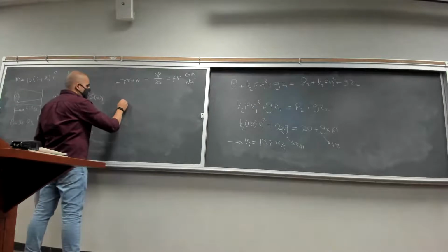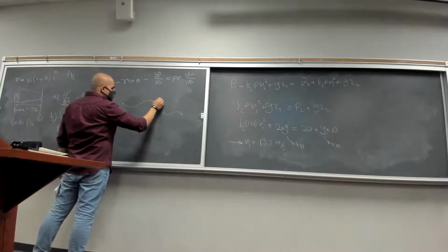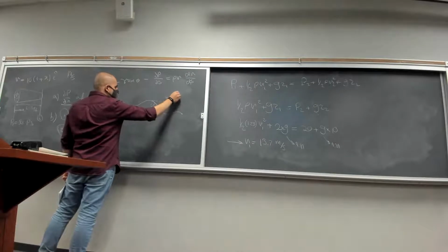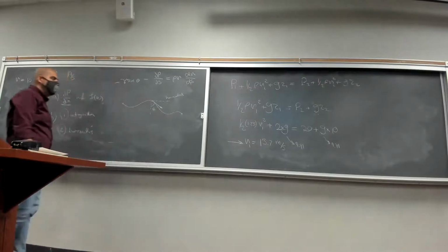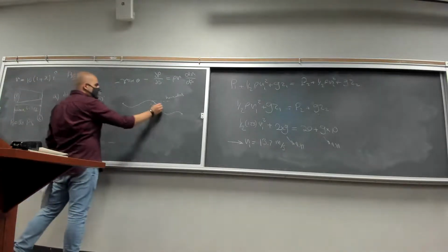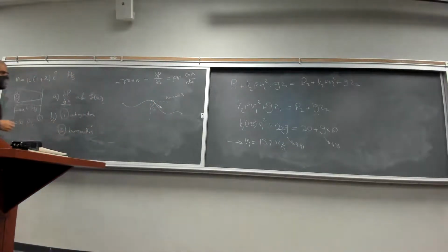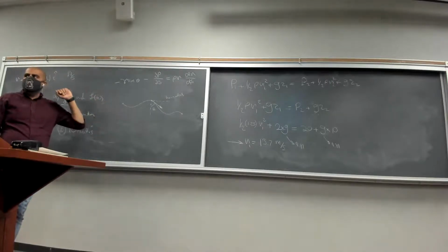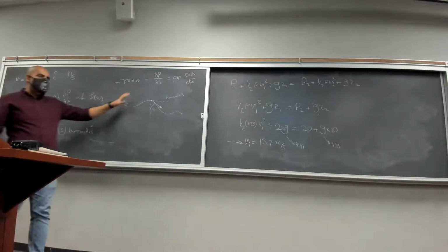What was this theta? If you recall, we started from a streamline, and let's say this is your horizontal direction. This theta was essentially the angle your velocity vector made on a streamline with the vertical direction, right? This was the general equation that applied to a very small point in a flow. Then we integrated this to get to the Bernoulli's, right? Since we are looking for a pressure gradient, we have to use this equation.